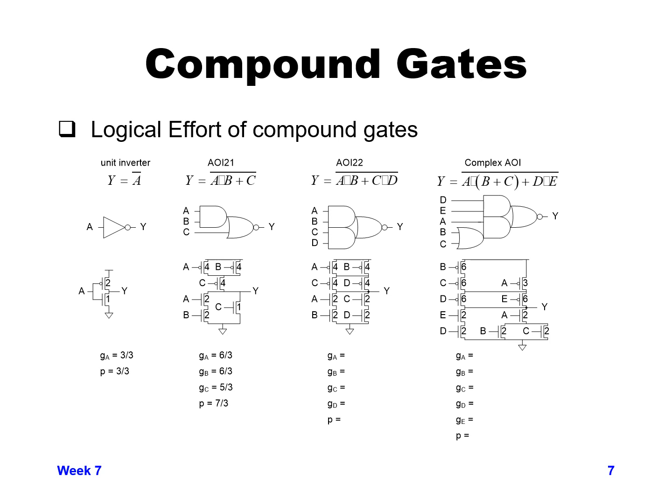In the third row, we have the transistor level diagram where, for the NMOS devices, the A transistor and B transistor are in series with each other. Since it's NORed with C, those two are in parallel with C, and then it's the flipped version of that on the top: A and B are in parallel and they're in series with C for the PMOS devices.